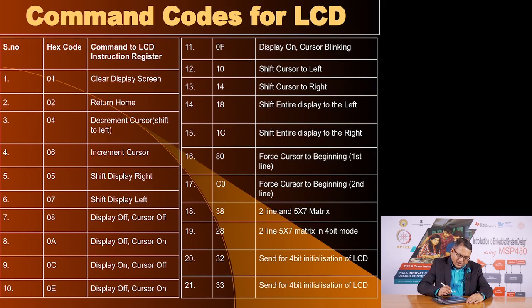Okay, so these are the commands. What commands can you send? You can send a command to clear the display. You can send a command to return to home. Home means the initial position of the cursor. You can increment or decrement the cursor. You can go forward or you can go backward and so on. So there are about 20-25 commands here, as you see, 21 commands, which allow you to interact with the LCD controller. Some of these commands we will see when we do an exercise. Let us go towards that.